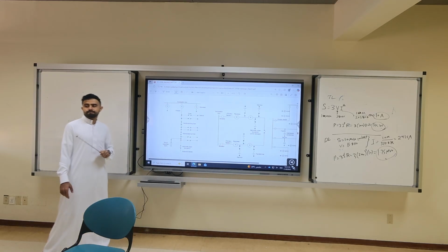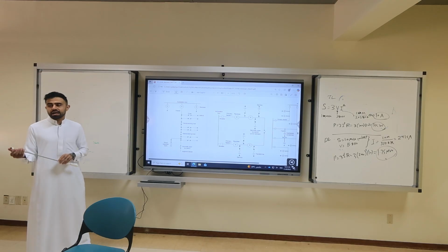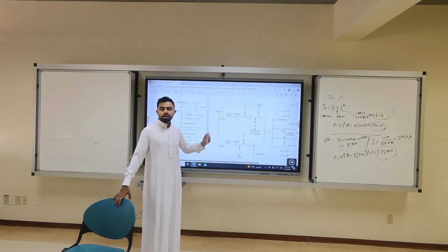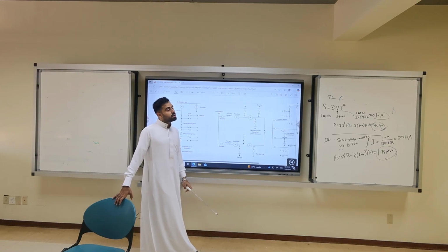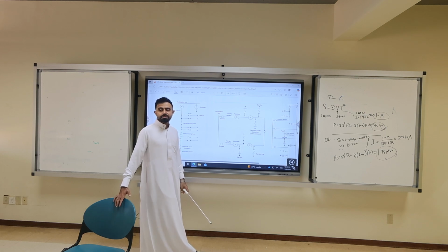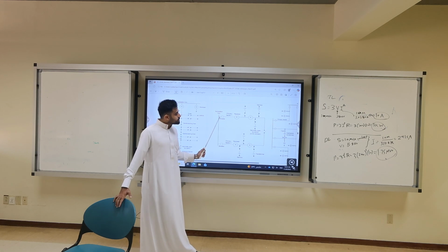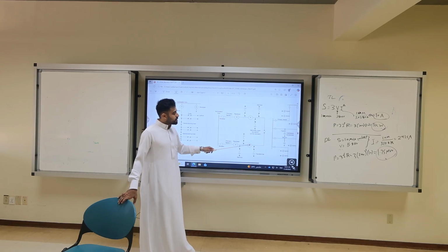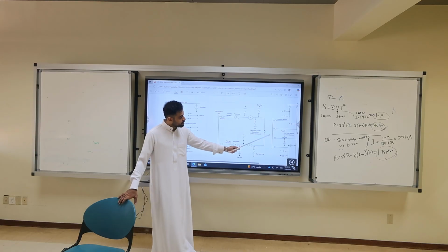Is there a recloser for almost every service? It depends on the design. You might combine 3 homes in one recloser, but normally it depends. Old system, new system, standard, non-standard. What we need to know is the loop is used to bypass. Same story: if we have a fault here, this recloser will be open. This will be open. Isolate this. Now no electricity will flow. You need to close it. Electricity comes from here all the way to here.